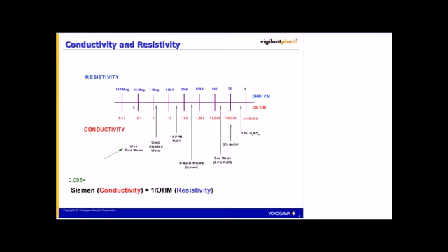There's a question: if you have pure or ultra-pure water applications, such as in power plants and computer chip manufacturers, some companies prefer to use resistivity of the process rather than conductivity, or vice versa. What would be the reason? The answer simply is preference. Some prefer to read very large resistance numbers, 15 to 18 megohm, instead of very small conductivity numbers, 0.05 microsiemens. However, the result's the same. It's just 2 different ways to look at the same measurement.